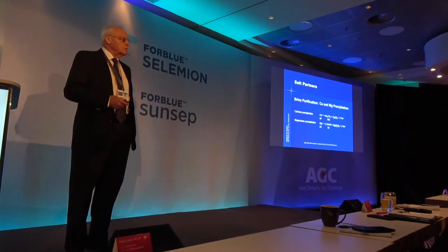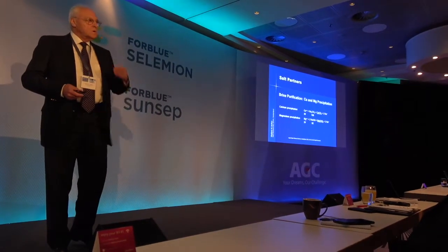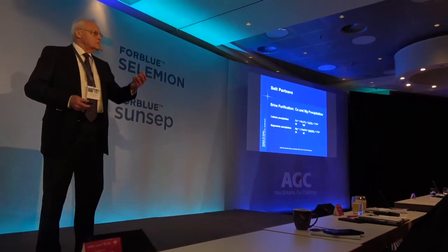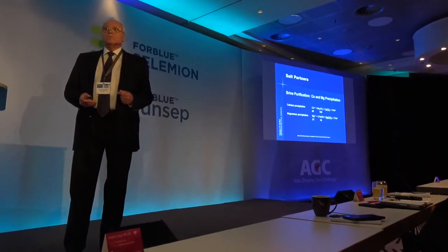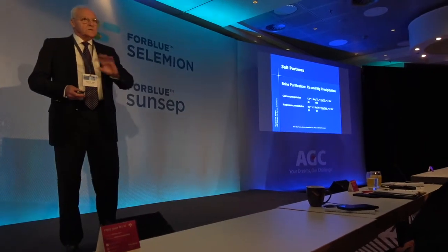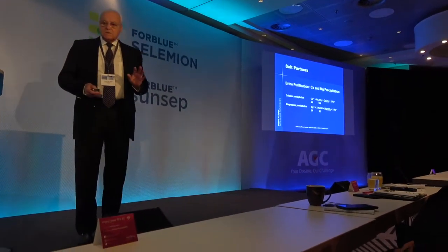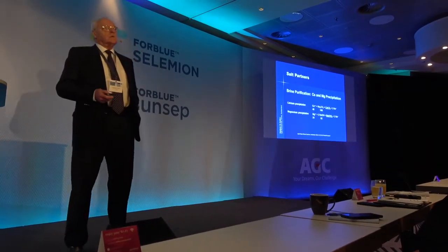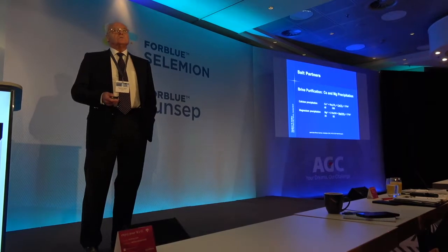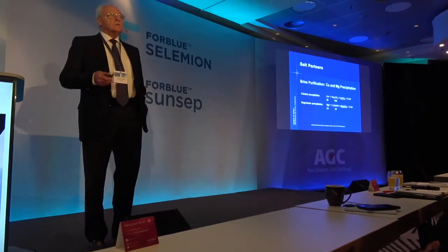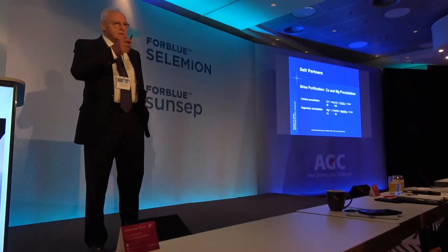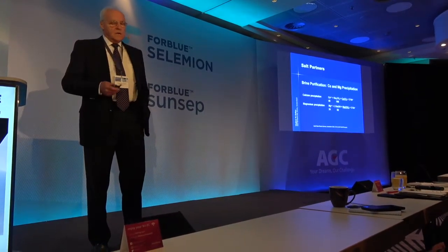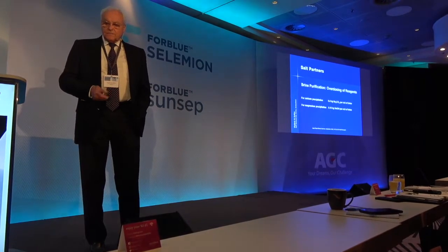It's like when you catch a cold and you are cleaning your nose, this is how magnesium hydroxide looks in the brine purification plant, and it blocks every filter. So it's a very nasty product, and the way to deal with it is to precipitate calcium carbonate together with magnesium hydroxide, and then it can settle quickly, and the rest can be reasonably filtered.